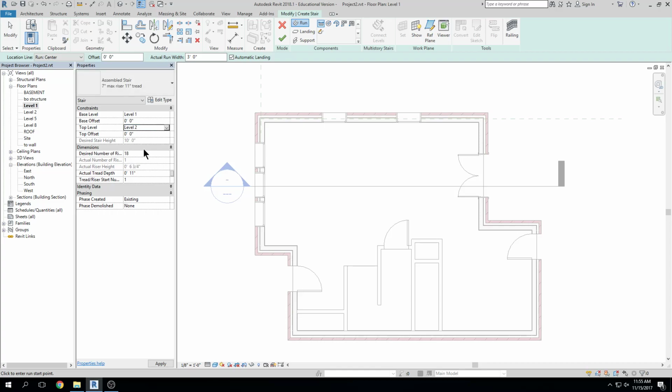I get into the stair, and it used to be that you could define the stair before you even got into it, like when you were in the sketch, right? So I could start my sketch and then define my top and bottom constraint, because a lot of times you forget to do that, right? And you start drawing along, and then all of a sudden you've sketched your entire stair, and then you think, oh great, I haven't defined the top and bottom constraint, which affects it, right? So Revit 2018 is a little bit less flexible in that. So right now, luckily I remembered to do it.